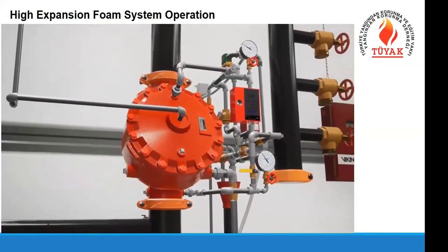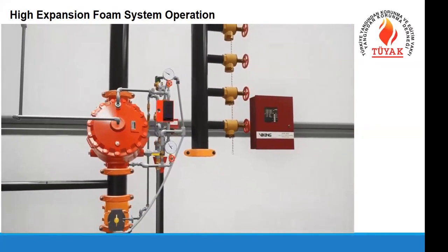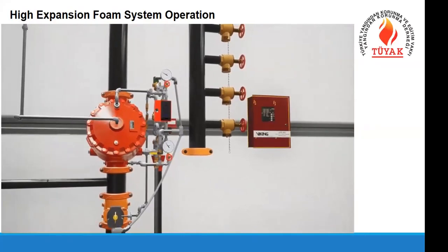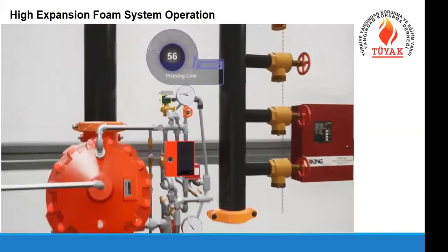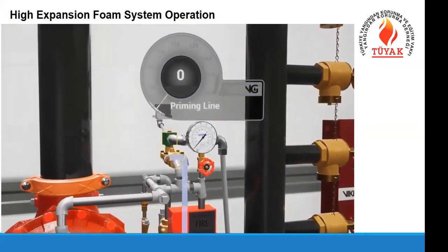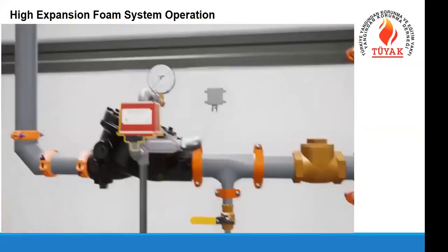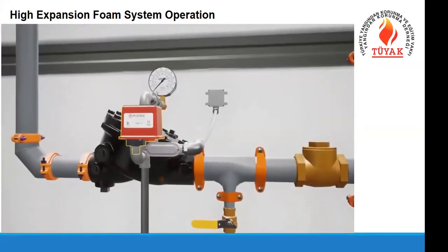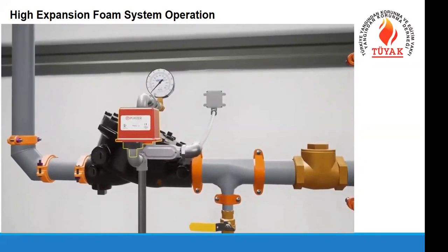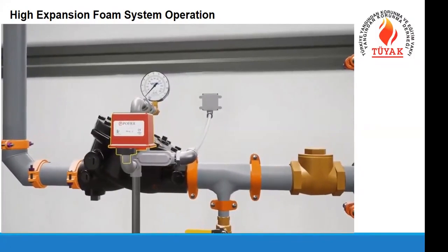In a scenario where a fire has started in the hangar and begins to grow, the electric detection device activates and sends a signal to the VFR 400 release control panel. The electric solenoid valve is powered open, releasing water pressure within the priming chambers of the deluge valve and the concentrate control valve. The drop of prime pressure causes the priming line pressure switch to activate. Priming line pressure switches are required for Factory Mutual global approval.